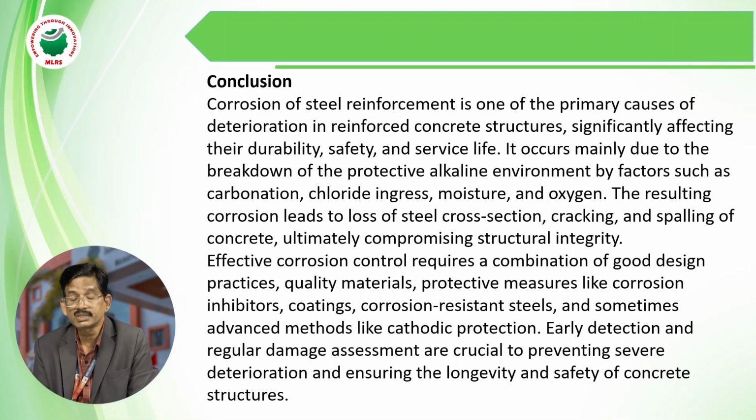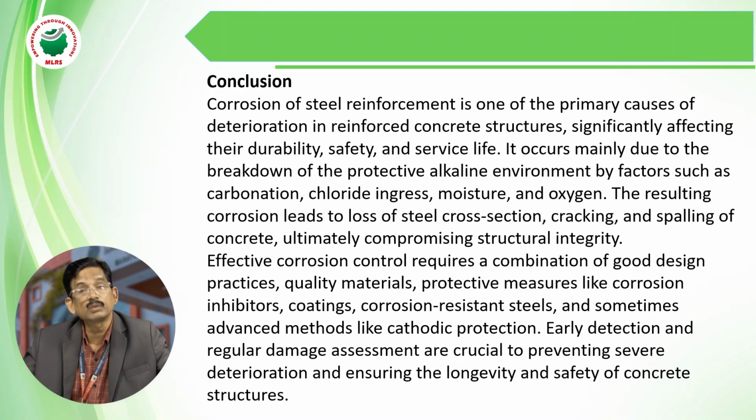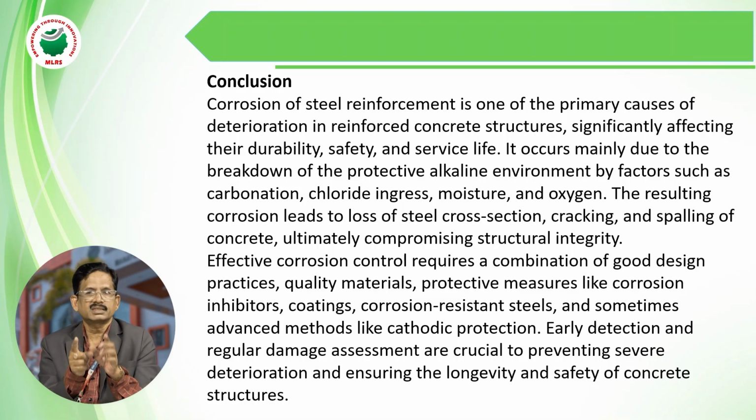Corrosion of the steel reinforcement is the primary cause of the deterioration of reinforced concrete structures. Deterioration means the strength is reduced over time, not in a particular day, month or year, and it significantly affects the durability aspect. My dear students, any structure will be designed against the strength aspect as well as the durability aspect. That's why we test concrete in the laboratory for mechanical properties as well as durability properties.